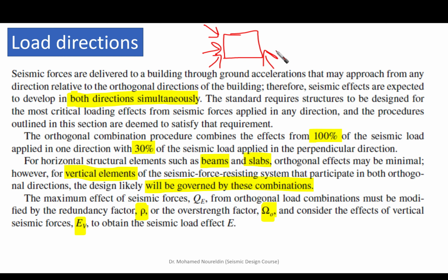So the point is, whenever we design, we need to be sure of the effect of the loading coming in the worst case direction. So maybe we can apply two simultaneous load directions at the same time. The orthogonal combination procedure combines the effect from 100% of the seismic load applied in one direction with 30% of the seismic load applied in the perpendicular direction.